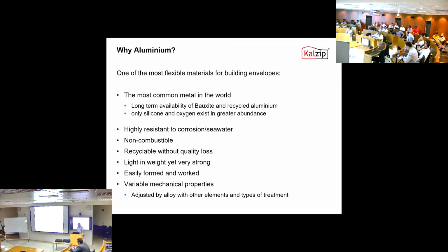Non-combustible, doesn't set on fire. Aluminium A1. Yeah, the alloy makes it non-combustible. Pure aluminium is limited combustible. It may melt, but it can't raise the fire. Not our aluminium. Pure aluminium, it's not a composite panel, so it's just a single skin of aluminium. It won't set on fire.